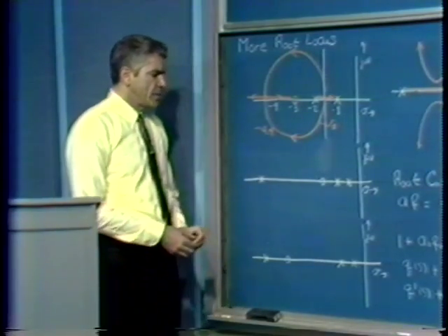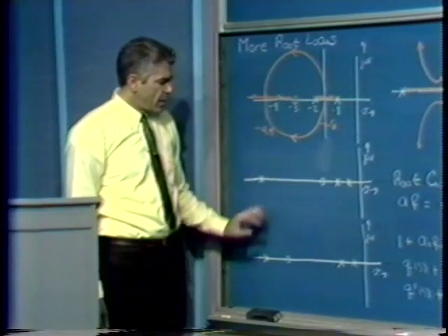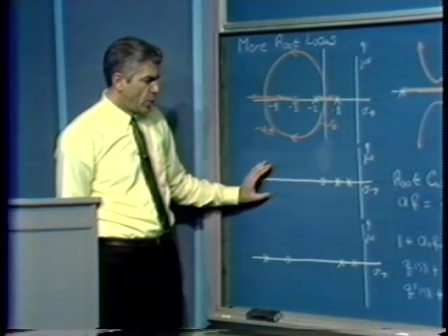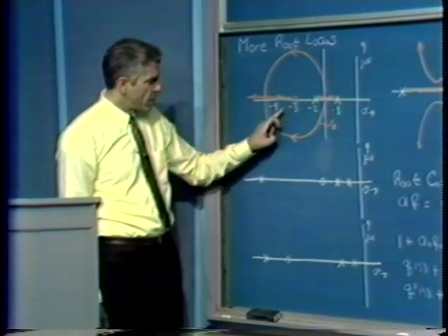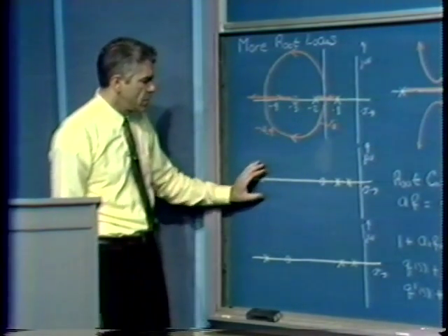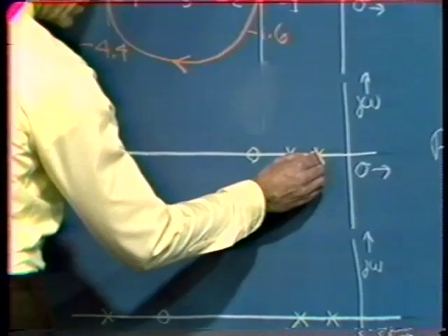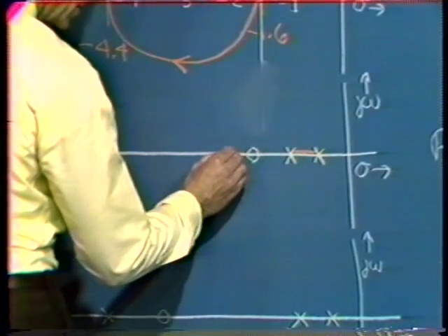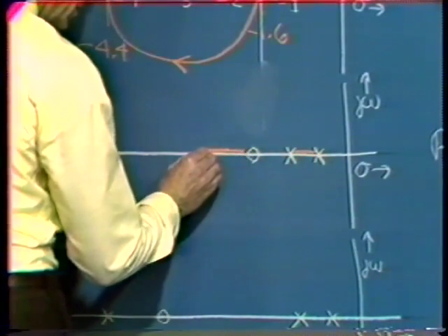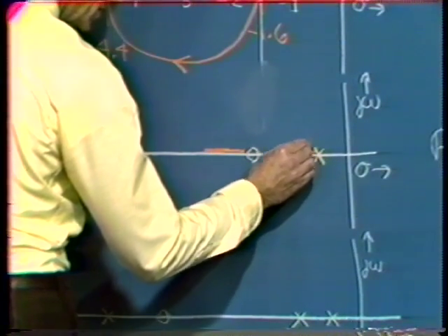We could determine the root locus initially by ignoring the remote pole, and under those conditions we get a root locus picture very much like we had above. So we'd conclude that to the extent we were able to ignore the third pole, our root locus diagram for this situation would look something like so, and a circle between these 2 points.